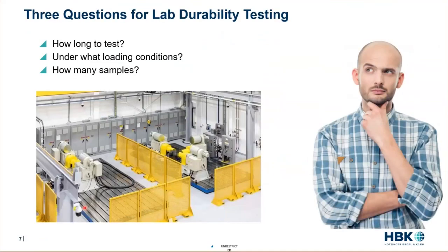So the questions that arise for lab durability testing are, how long do we test for? Given my product's life cycle, given my product's profile, how long do I test for? What are the loading conditions? What are the temperatures? How much torque, how much speed? What are the ramp rates? And then how many samples?